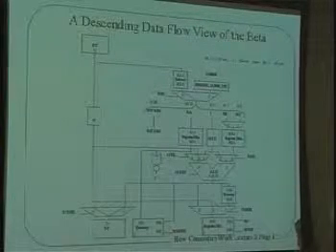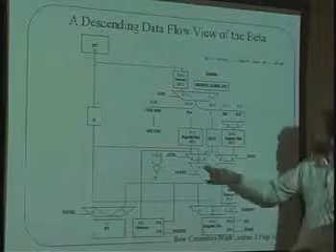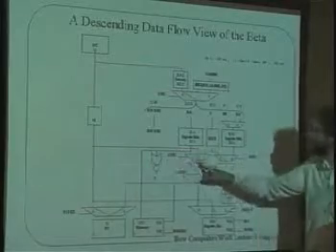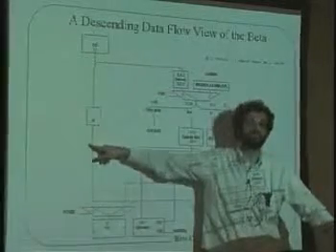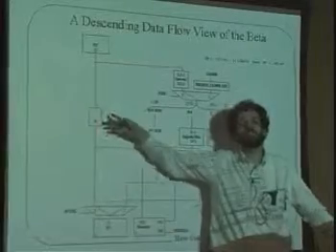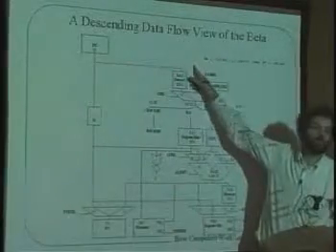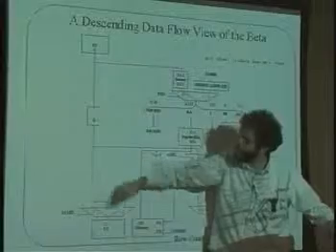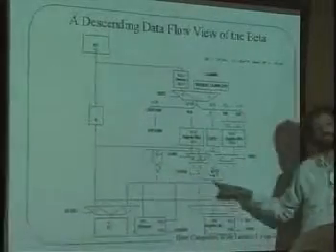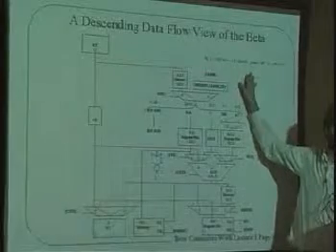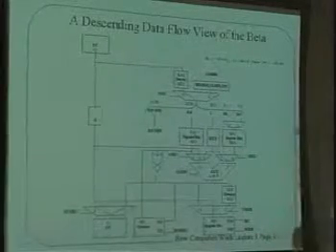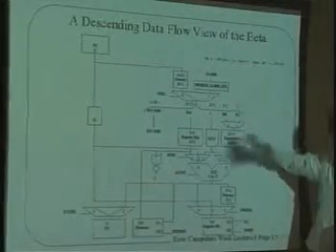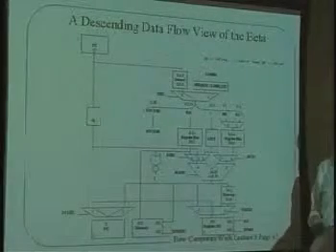And the way that you're not going to be able to know the difference is that the sum that this guy does of the constant with something to do with the PC, I could have had this path choose the PC before the plus 1, and it would have chosen the PC before PC plus 1 was put into PC. But instead, I choose the data having to do with PC plus 1, in other words, what's about to be written into here. So the effect is as if we did them one after the other. Okay? So the functional description is one of these happening in sequence, but the physical implementation is that they happen at the same time.